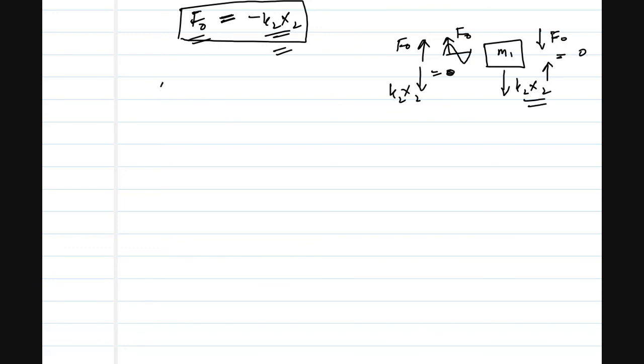Now it's also called a tuned mass damper, and if you look at this word, it correctly fits the definition. Tuned means you have tuned the frequency of the absorber. Mass damper means your mass actually performs damping. Your mass acts in such a way that it reduces the vibration, which is the purpose of a damper. That's why it's called a tuned mass damper. Tuned means it's set to a certain frequency, that is, omega is equal to omega 2. And mass damper means the mass acts as a damper.